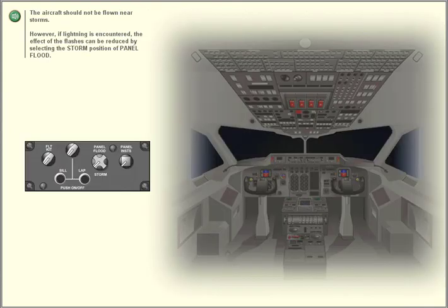The aircraft should not be flown near storms. However, if lightning is encountered, the effect of the flashes can be reduced by selecting the storm position of panel flood.